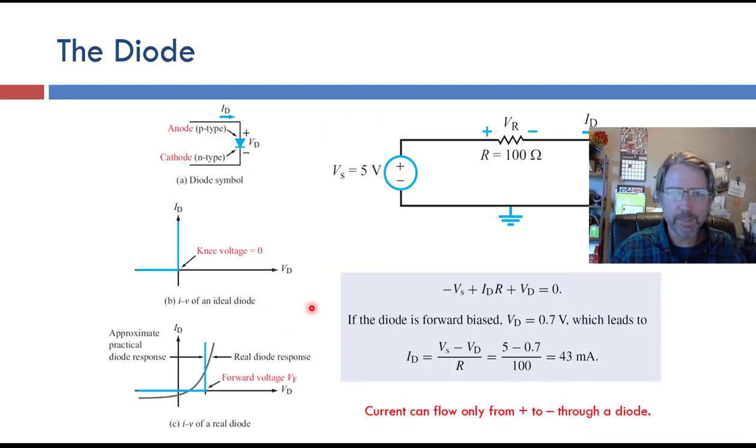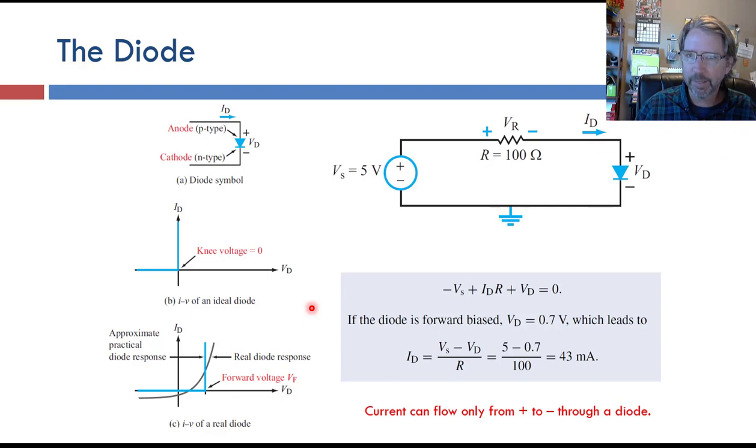There are other components. Semiconductors come into play here. The diode is an element that you'll see more in the lab than in lecture. The diode is used normally to block current from flowing in one direction. If you're thinking of hydraulics, it's like a check valve. The diode symbol is an arrow, showing that the current can only flow down in this one. And the little whiskers here are, if you look at a diode, it has a stripe on one end, and the whiskers are the end that has the stripe.